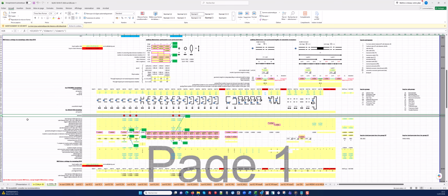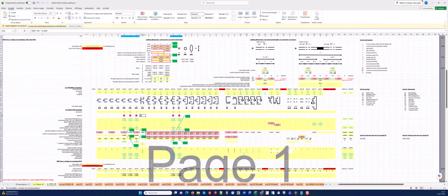Here we find again the highlighted elements of our mountings numbered from 2 to 6. 2, 4, 6 are uniform tubes. 5 is the extended inlet, and 3 is the extended outlet. All the dimensions relating to diameters are displayed here automatically. And what we need to enter is only the geometrical length.